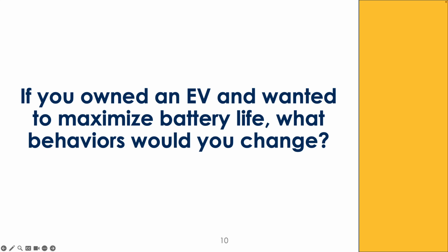Any other questions or comments? Yeah. When you said extreme temperatures, high or low, are bad for the battery, is that just when the car is running, or when it's charging, or all the time? So kind of all the time, but when it's operating, the effect is maybe a little bit more pronounced, because you're actively charging or discharging the battery. And doing that at temperature extremes is going to be worse.